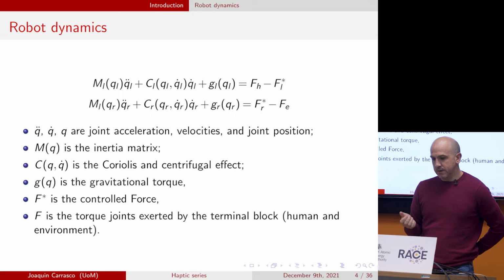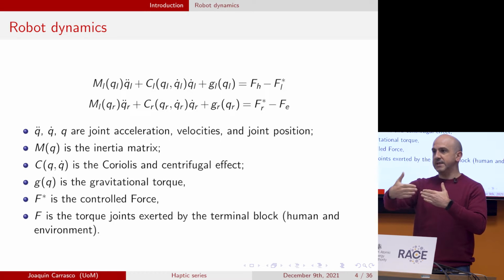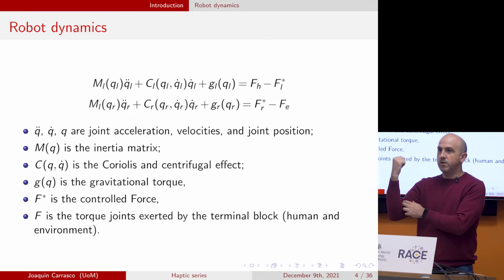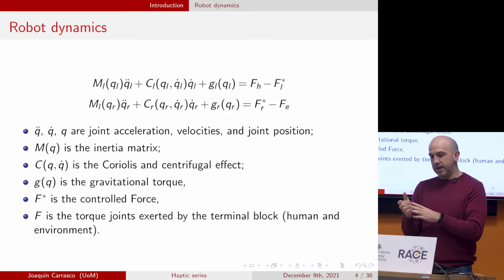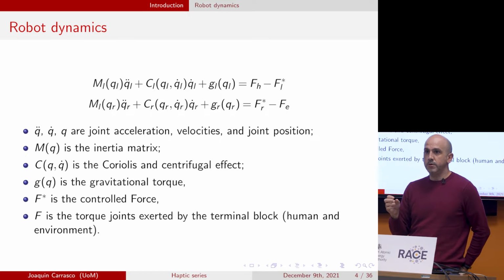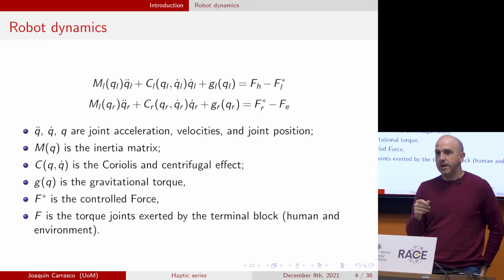Because we can have angles and prismatic variables, if you have a prismatic joint you are speaking about a translation, but if you have a rotation joint you are speaking about an angle. In order to use both translation and rotation in just one single symbol, we normally use the symbol Q to represent the vector with all the different joints of my robot.